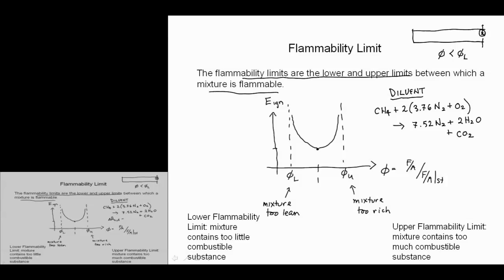So this looks like about 44 kilojoules per gram of fuel. All that energy has to be able to increase the temperature of the product gases. And this is, again, from our enthalpy versus temperature graph. So that's the stuff that allows us to increase this.